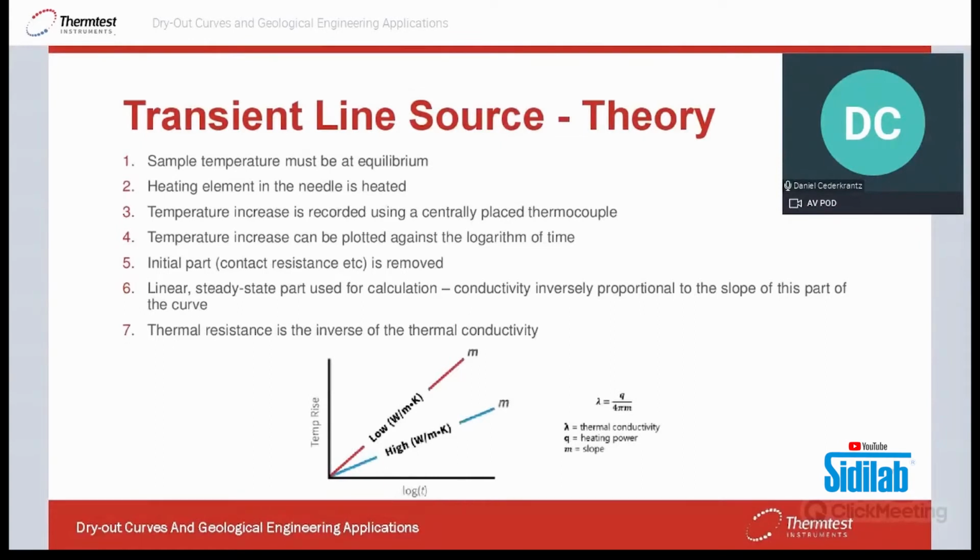If you're in the field and do tests, you should take care where you do your testing. If you're in a trench, make sure you're perhaps in a shady area. Don't move a sample from the shade to the sun and so on, because this will change the temperature of your sample and influence your results.